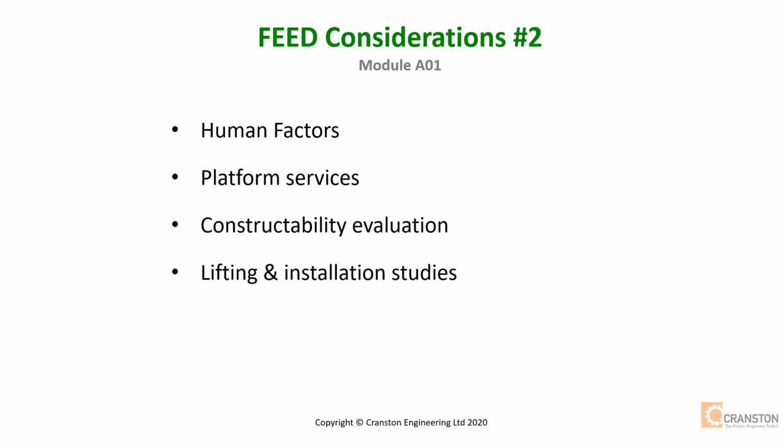Two installation options: a single heavy lift via crane barge or modular installation using the platform cranes. If you're opting for a single lift, this will be the time to engage a heavy lift contractor to ensure that all aspects of lifting, including site clearance and protection bumpers and guides, are considered and included in the project scope. For a modular lift using the platform crane, this will involve liaison with the crane subcontractor and possible maintenance and modification of the crane to ensure lifting capacity and wind and sea state limits are maximised.